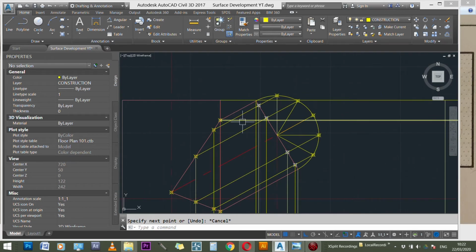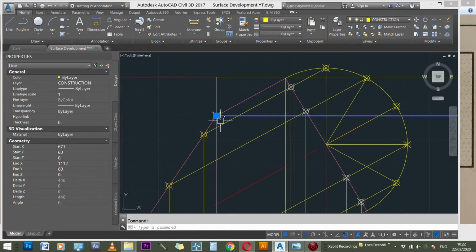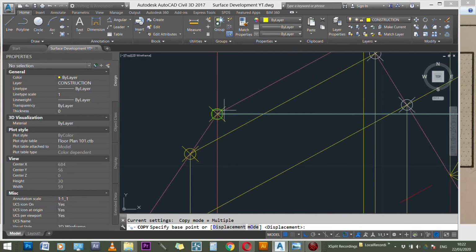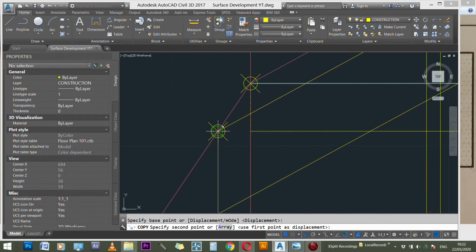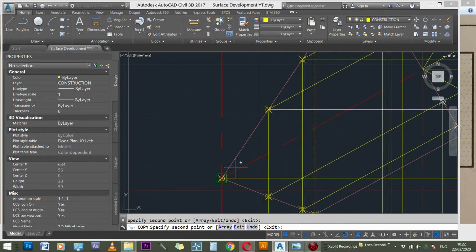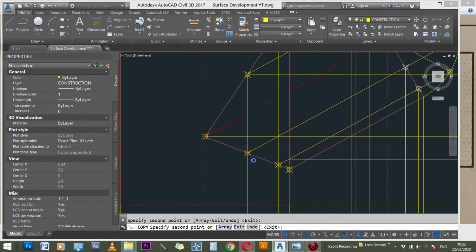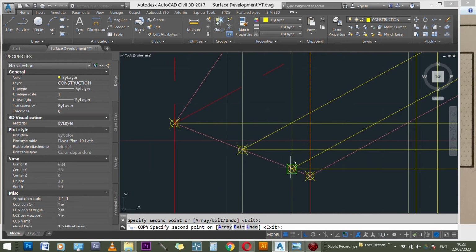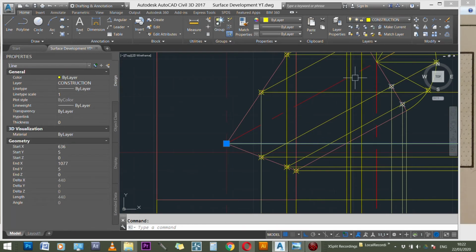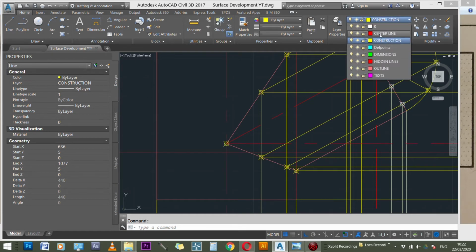Project them over to the circumference surface that I'm going to be working with. So let me just copy, because I'm not going to be drawing these lines individually. Just copy from this point to these intersecting points. And it's always best that while you're copying over, you copy everything in the construction layer, but you always place the center point on the center layer, right?